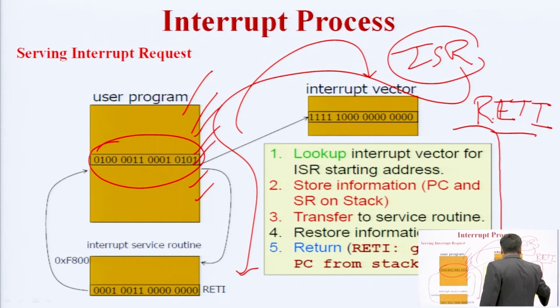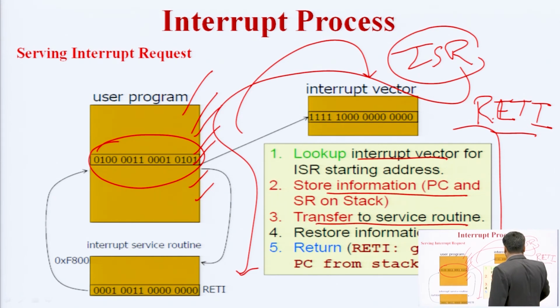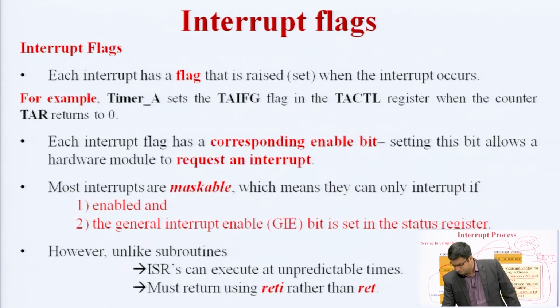So how can we control the interrupt? Through some software programming: look up the interrupt, store information into the SR, transfer to the interrupt service routine, restore the information, and return from the interrupt. These are the programming concepts.